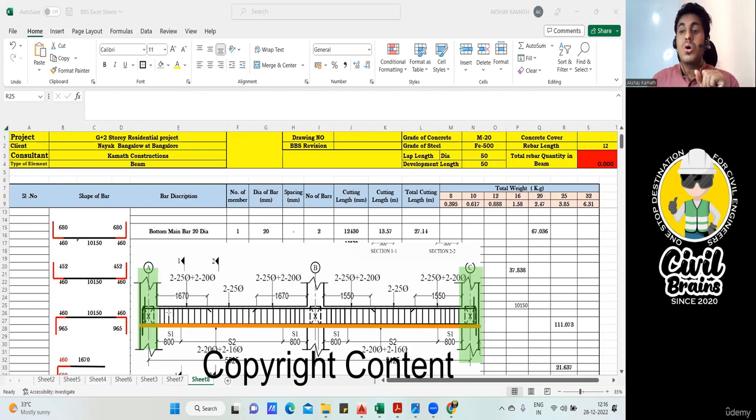So what is the cover for the column? It is 40 mm. Right now I'm doing only the left side. The column width is 500. From 500, if I remove one cover, I'll get this length. I want to find this horizontal length from here to here, but I won't take the complete length, because then I'll not get the cover. So I'll stop up to here.